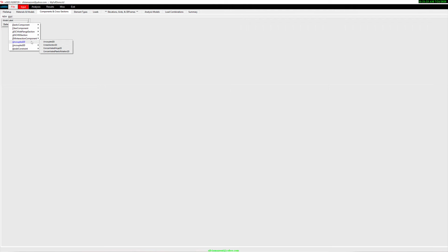It really depends where you define. So I would always just jump straight to the 3D model, where you can have a cross section, a concentrated hinge, or just plastic rotation. These are kind of the same type of material and behavior, but it really depends on if you're going to put them in a lump plasticity element. You've got to use either the plastic rotation or a concentrated hinge. You don't want to use a cross section because it will not do the proper integration. And then I also have nodal constraints, which are not really springs. You define the springs as fixed or free.